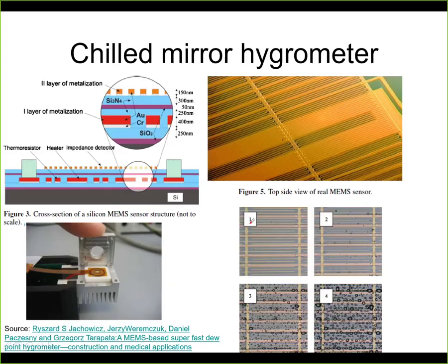It typically looks like this. It does not have to be just an optical detection, but we can detect also changes of capacity, which you can see here. So let's start here on this picture on the bottom right. This is the surface as we will see it without the dew on the surface. Here there are no water droplets, and as the temperature of the surface is dropping, we see that we have more and more water droplets on the surface. This can be detected optically, or as in this case it is detected as capacitive changes.